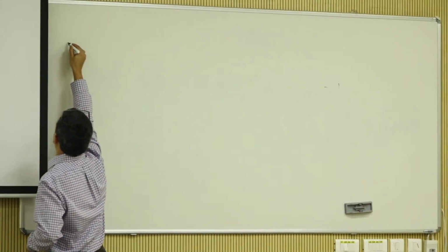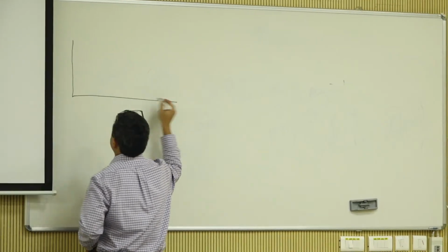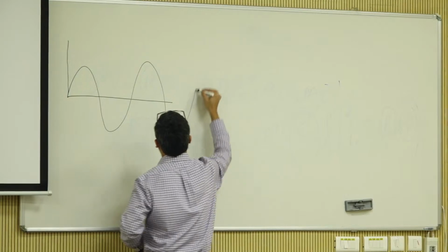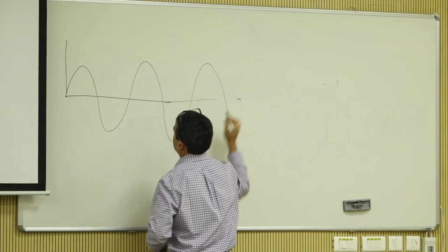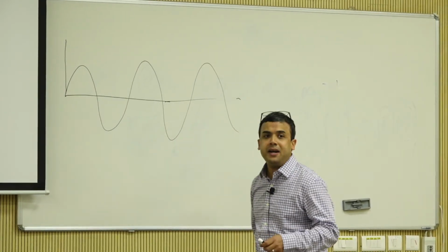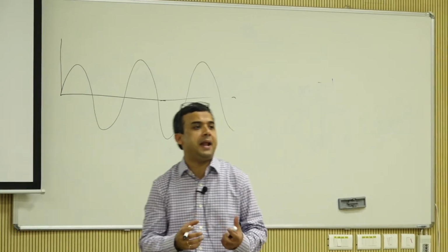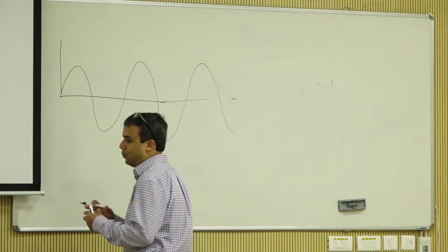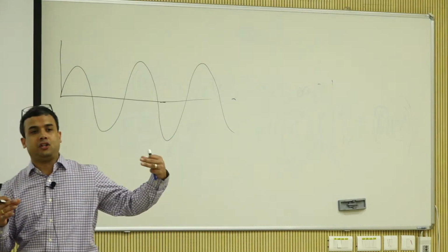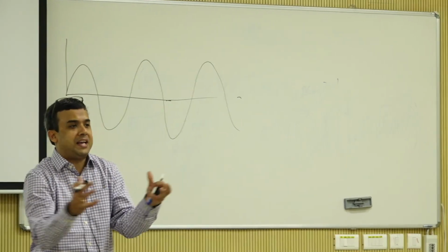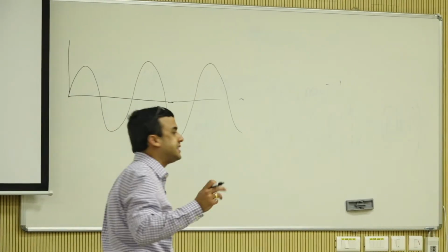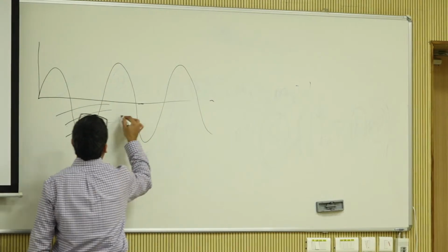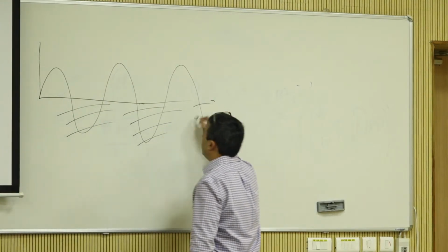Just for documentation purposes, if it was a cyclic load, then you would have this. In a pavement, you are not really applying tension to the material, although you can argue that, when you have the moving wheel load, there is a little bit of extension happening, but it's not really cyclic loading. So we don't call it cyclic; we remove all of this, right?